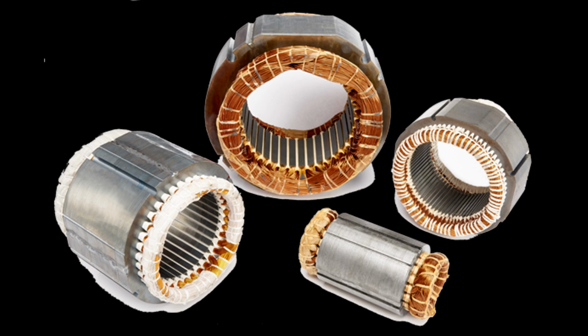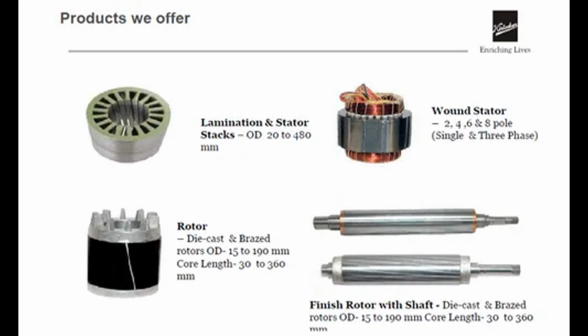In summary, the stator is the stationary component of an alternator that consists of coils arranged to receive the rotating magnetic field generated by the rotor. This interaction between the rotor's magnetic field and the stator's coils results in the induction of three-phase alternating current, AC, electricity, which is then converted, rectified, and regulated for charging the battery and powering the vehicle's electrical systems.